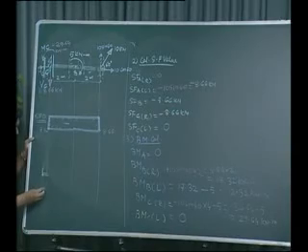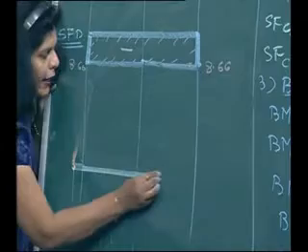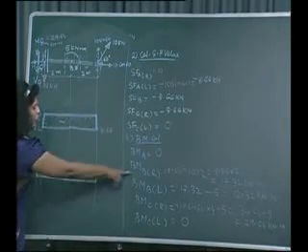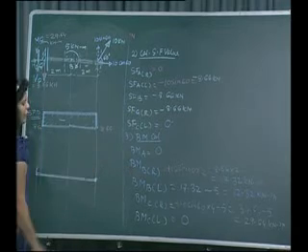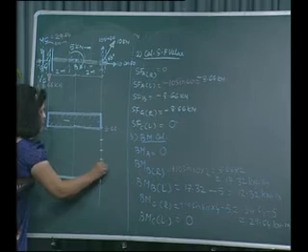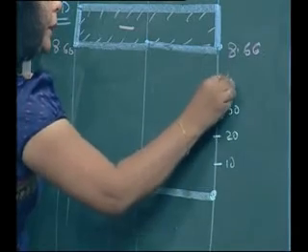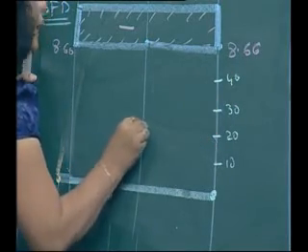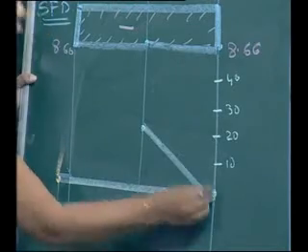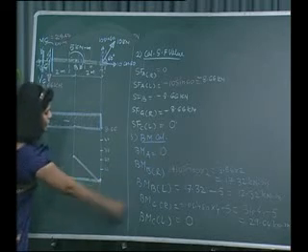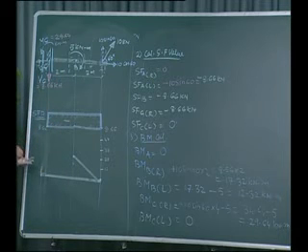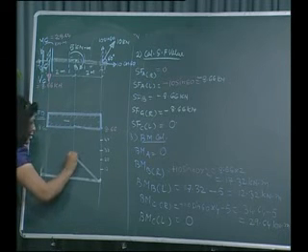So to draw a bending moment diagram, we will draw a baseline, then bending moment at point A 0, bending moment at point B just right 17. So 10, 20, 30, 40. So 17 will be somewhere over here. What is acting? No load between A and B. It will be an inclined line. Bending moment at point B just left 12.32, somewhere over here. What is acting? Couple. So it will be a vertical line.